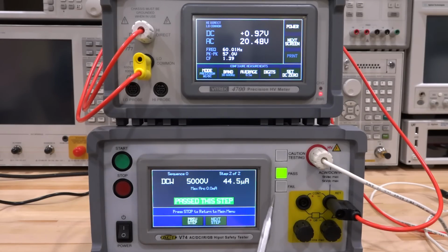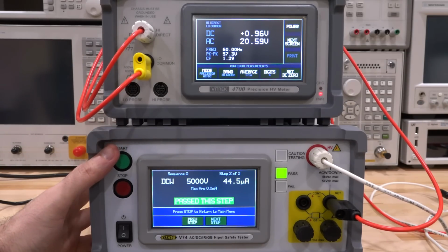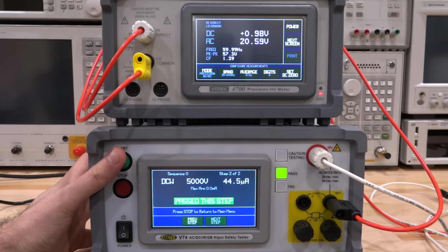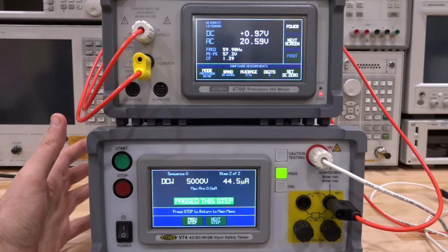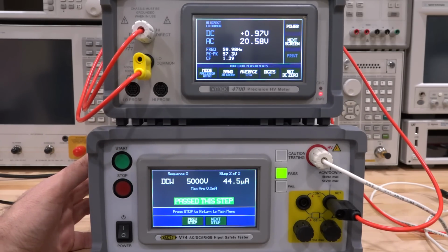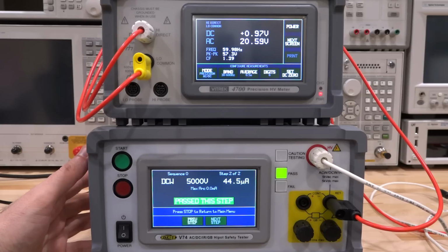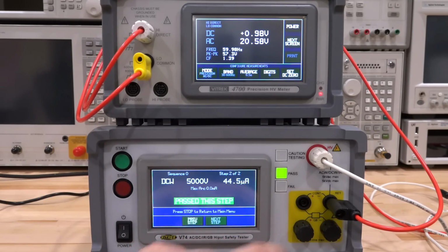Now you may be wondering what these other ports are here at the bottom, but they are to measure the integrity of a ground connection, for example, to a chassis. In many situations, the chassis of an instrument is grounded, and therefore if there is ever something shorted to it, the fuse would pop because the current will go through the ground, and then the fuse will eventually probably go over the amount of current it's supposed to have. But now imagine if that ground connection is made with a very skinny wire, something that would pop, let's say, with 100 milliamp. In that situation, a short condition would just simply burst open that line and the chassis can become live. In this situation with this one, they apply 10 amp through a chassis to make sure that its resistance is very small and it can maintain that amount of current to go through it. It is also part of the safety test.